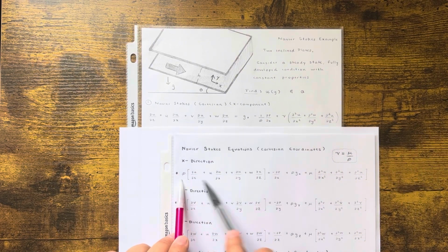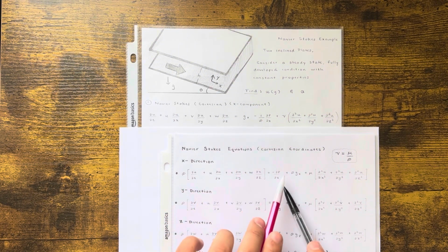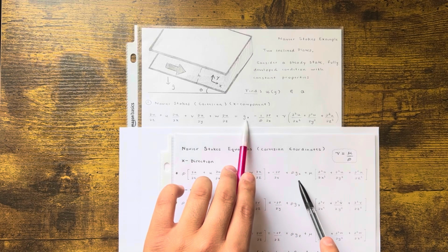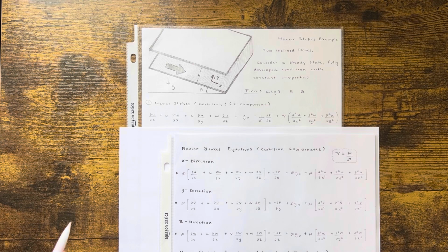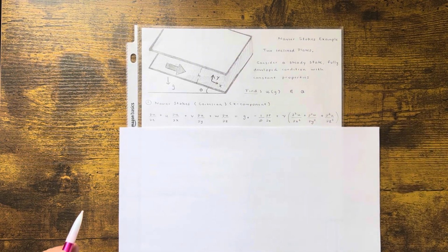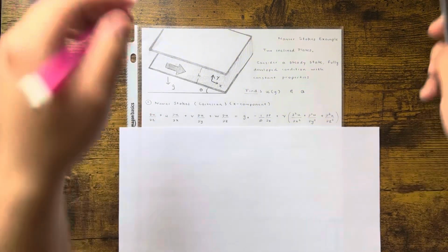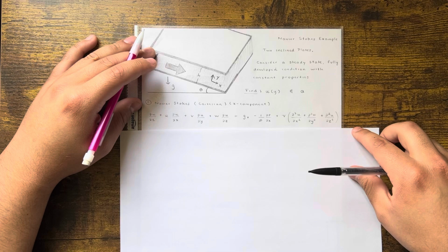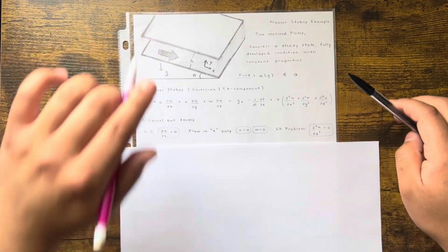I just like to divide density into everything. So this will get a -1 over density. The rho cancels out with this rho, so you'll just get g of x, and that mu, because of this relationship, will turn into nu. If we do that, this is what we get. Now, we have to start canceling out the terms. This is easy. If you watch the previous videos, you know what I'm talking about, but I'll go ahead and do it one last time for you guys right here.